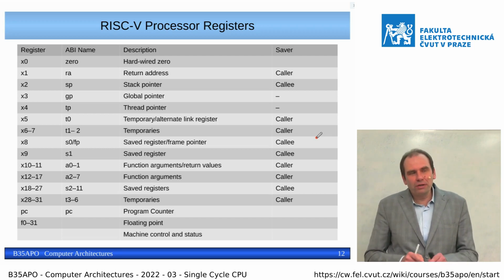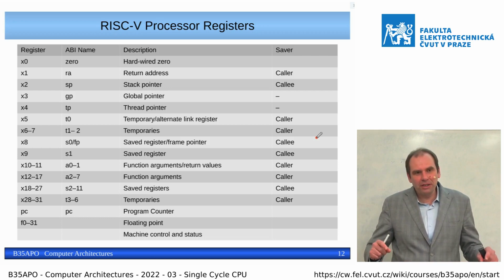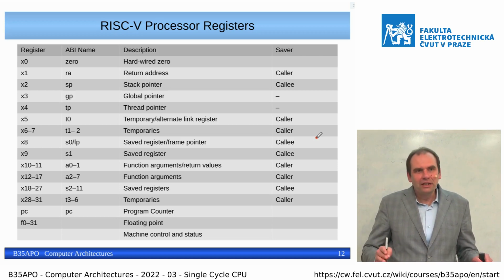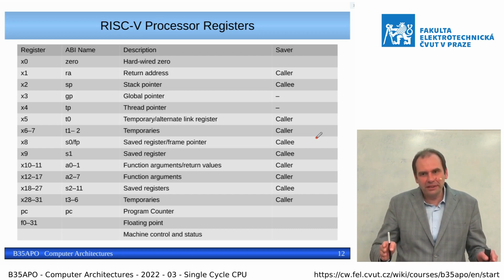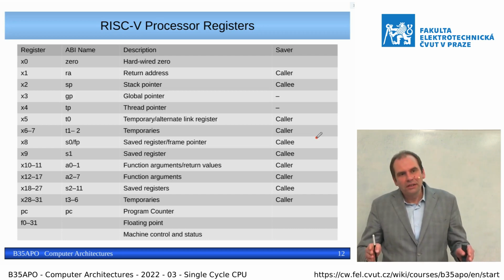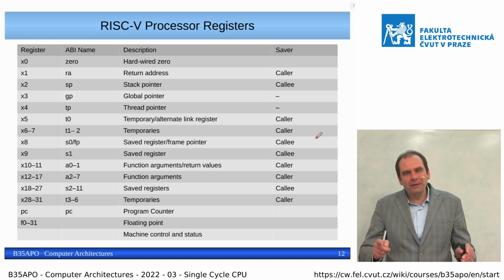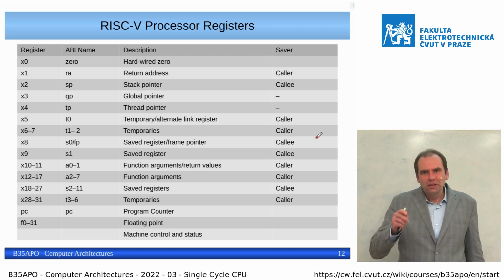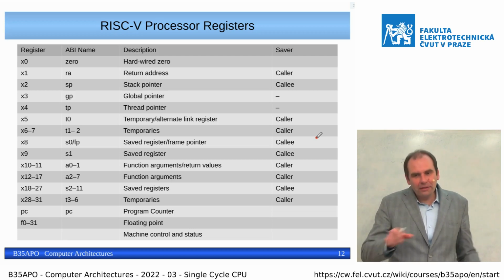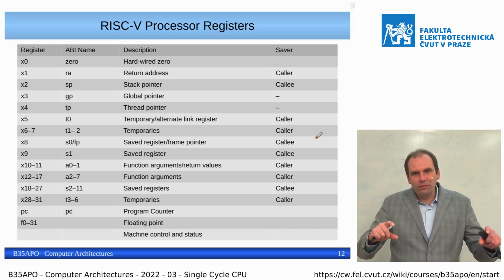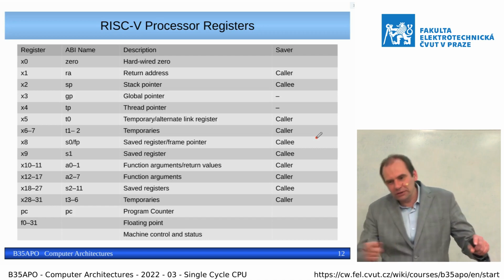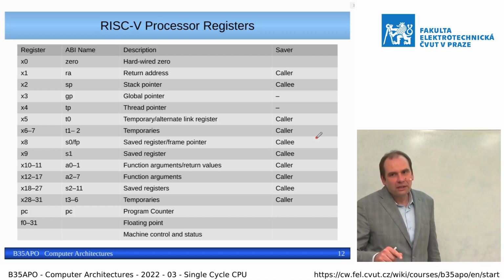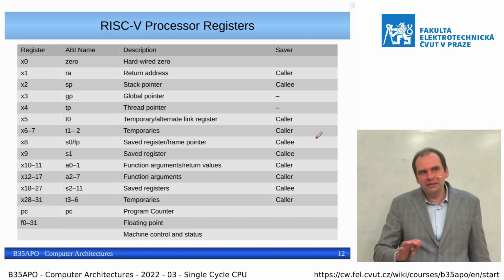But the actual organization of the memory is usually today 32 or 64 bits in width. So yes, there is a problem if 1/2 of the instruction falls at the end of one 64-bit word or 128-bit word, and the other goes to another address. But it is hidden by the hardware.